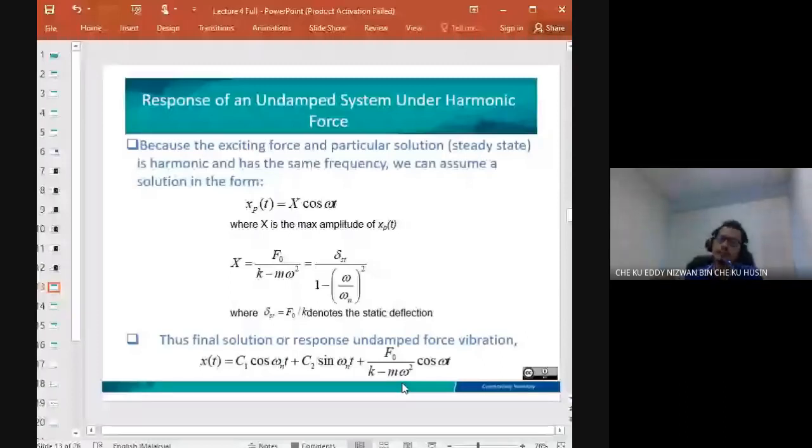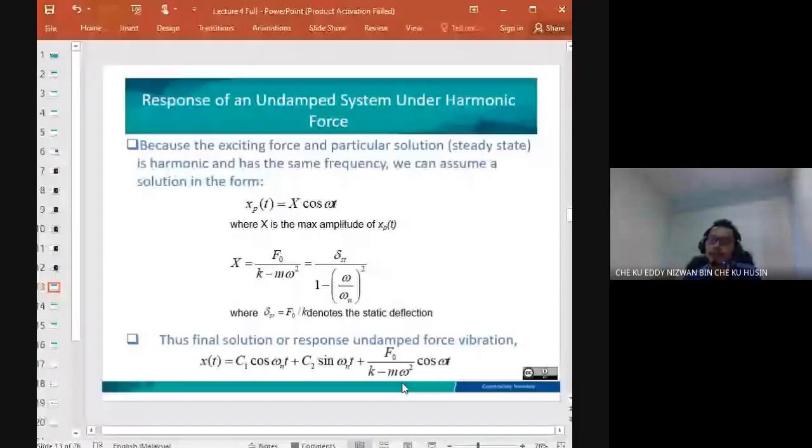So you can stiffen the structure, add spring elements, or put additional mass to control the natural frequency. But normally most of the solutions are to stiffen or loosen the structure, which controls the stiffness of the structure. That's the common practice to solve the high vibration issue in industry.